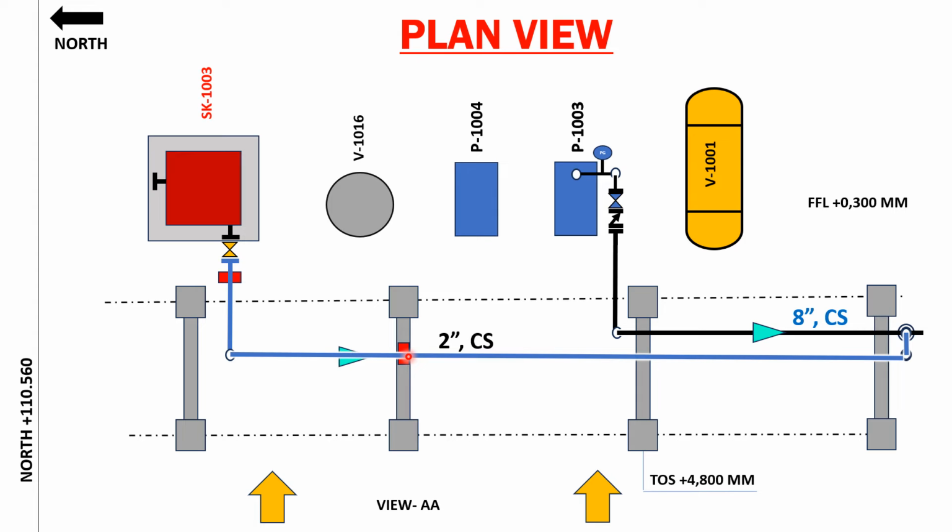the pipe tends to move, your pipe will have a rubbing tendency over the pipe rack. So that will take off some material. So there will be a tear below the pipe if it is not provided with a shoe support. If you are providing a shoe support, then the shoe is going to slide over the pipe rack, so that you don't have to worry about the failure of the piping, right? So generally we call this a rest support.